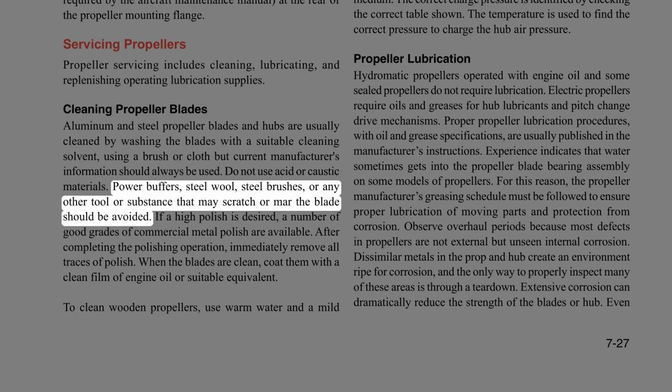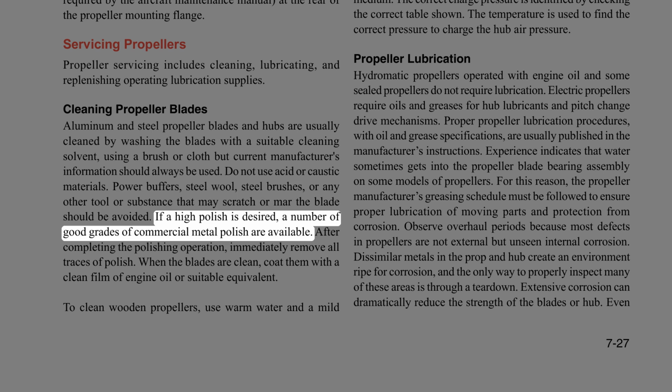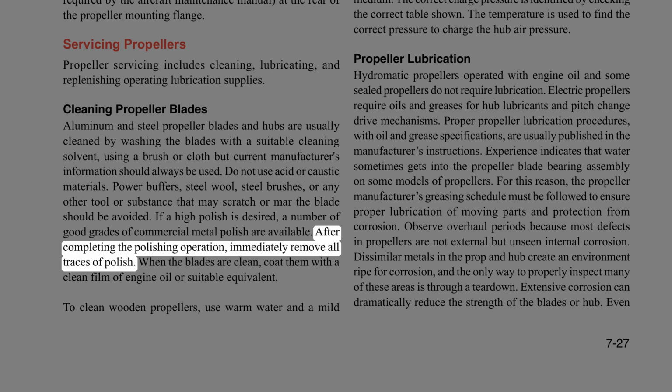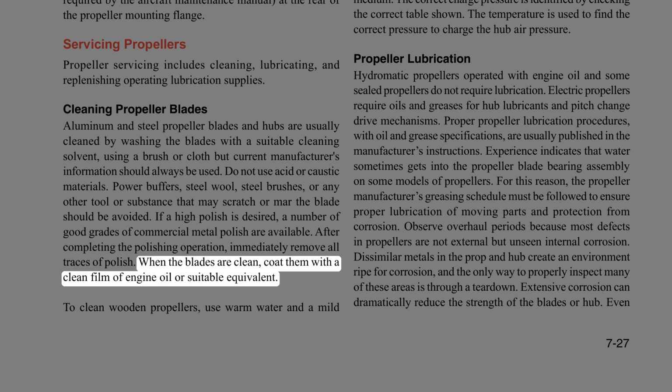Power buffers, steel wool, steel brushes, or any other tool or substance that may scratch or mar the blade should be avoided. If a high polish is desired, a number of good grades of commercial metal polish are available. After completing the polishing operation, immediately remove all traces of polish. When the blades are clean, coat them with a clean film of engine oil or suitable equivalent.